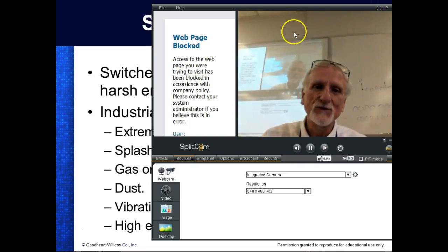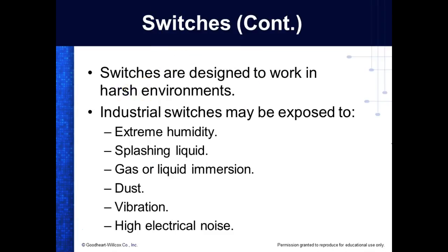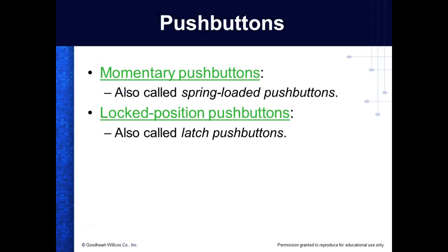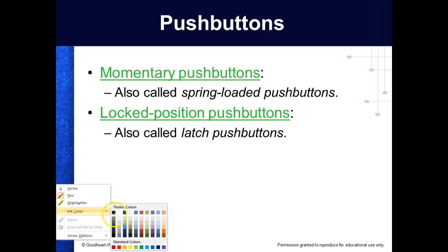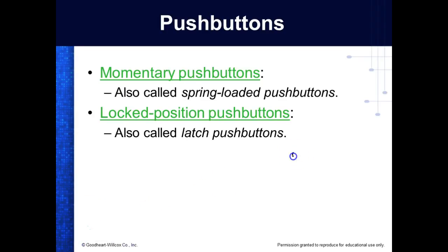Well, when we draw the limit switch, this is where we start using that second symbol. The symbol for a limit switch is we basically come over here and draw it like this, no matter what the operator is. So we draw this, which would be normally open, and then I put this little V right there. That's the symbol for a limit switch, and this would be a normally open.